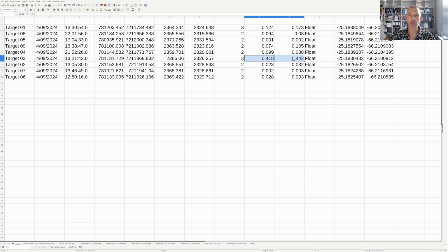The error pretty much directly correlates with the duration of the measurements. If you measure your reference point for a couple of minutes only, you may have centimeter or a couple of centimeter accuracy. If you're measuring for more than 10-15 minutes, you get into the lower centimeter, sub-centimeter level of accuracy.